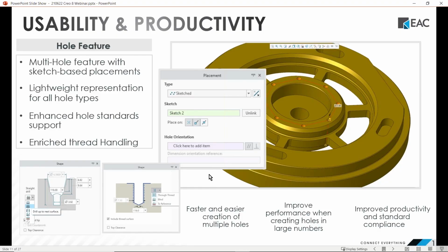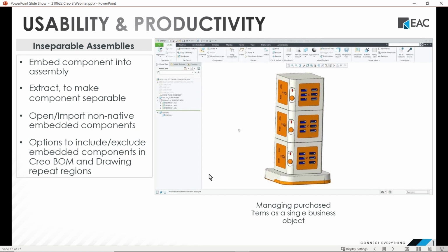Going back to our PowerPoint, this is a new capability as well, and it's kind of bleeding in the way I look at it, some existing technology that's been around in Creo forever. A lot of times, if you do an assembly feature, do an assembly cut through multiple parts, the assembly file itself is pretty much empty. There's no geometry in it, just a bunch of pointers to all the parts that are in that assembly. But as soon as you do assembly cuts, any of the parts that are affected by that cut get copied into that assembly file. And so then you got pointers and geometry in those. So the assembly file gets larger.